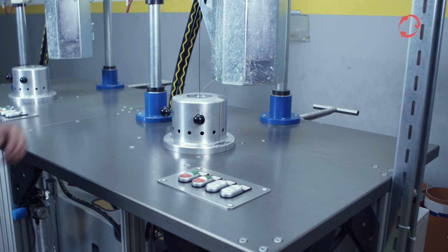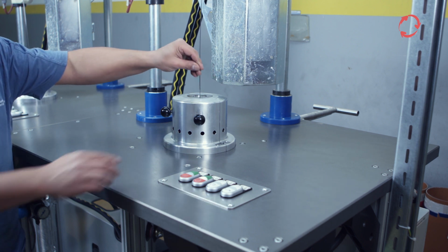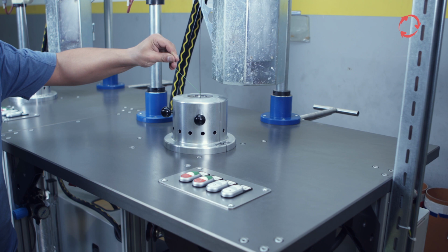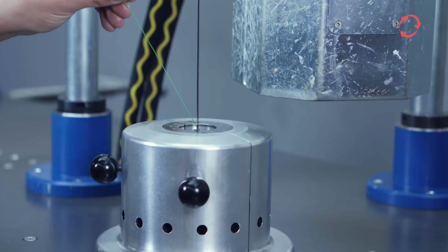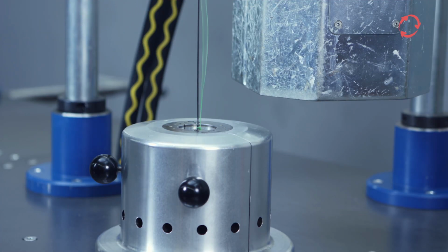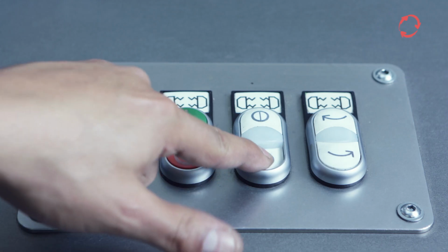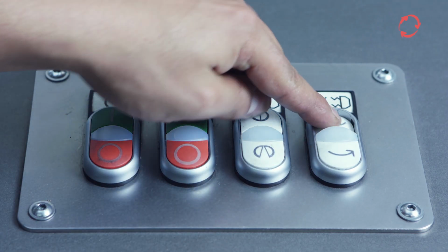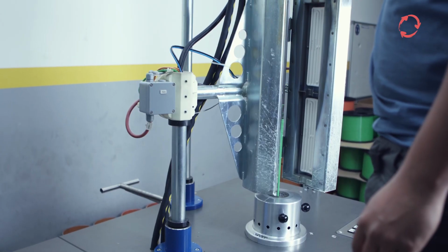Once the heater has reached the target value, the spindle can be started by pressing the green Start button on the top of the machine. When the spindle starts running, the tied spiral wire must be secured with 2 fingers during the first rotation to prevent it from winding onto the mandrel. Open the heater while the spiral is in the upper position. Now swing the heater to the mandrel.